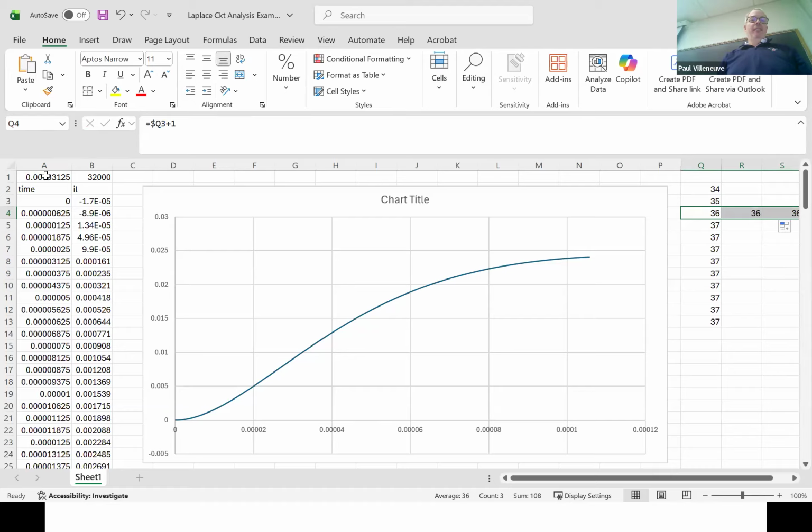Or, like I said, for me, just call that one tau. Even if you click over, watch very quickly. Look at the letter that you see up in this column right here. See, it says A1, because Excel knows that as A1, but I've reassigned it as tau. It takes a second for Excel to do it, but anywhere you see tau, it just makes it A1 and puts the dollar signs in for you. So it's a really helpful feature, especially when you're doing a lot of engineering stuff with all these numbers and variables. You just fix it by calling it a variable.